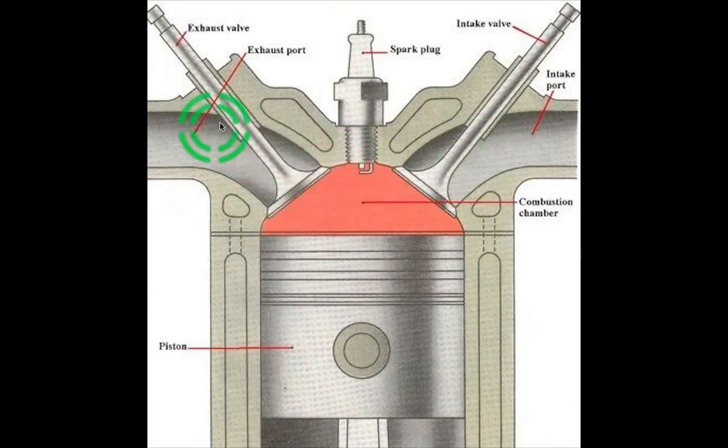So this is your exhaust valve and this is your intake valve, right? Let's say you have enormous pressure coming in, and an injector is spraying all day. Can it pass through? No, it can't, because the valve is sitting. As soon as the camshaft pushes this valve down, it moves forward and now you'll have some room on the side. Then the enormous pressure which was sitting right in the back, trying to make its way in, as soon as the valve goes down, it's going to push and go.